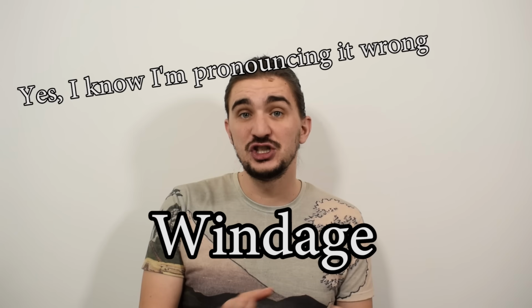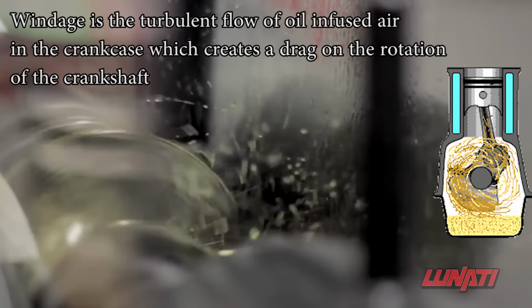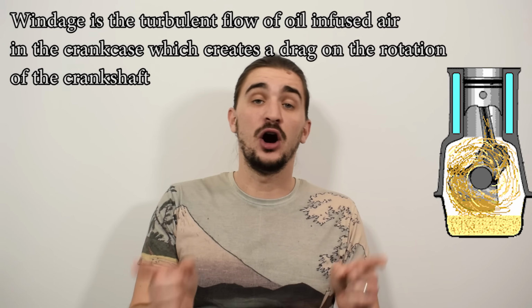Another important thing when it comes to performance engines and crankshafts is the shape of the counterweights themselves, and it needs to be as aerodynamic as possible to combat windage in the crankcase of an engine. Windage is the turbulent flow of oil-infused air within the crankcase that creates a significant drag on the rotational motion of the crankshaft. A more aerodynamic shape of the counterweights is going to ensure less drag.